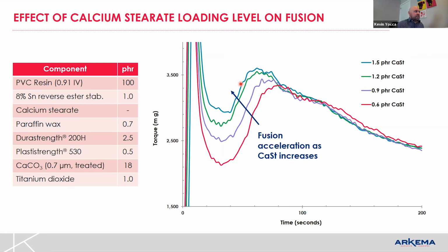Now, beyond these lubricants, there's obviously a library of them, from esters to complex esters, even mineral oils and other things. ESO can be used as kind of a co-stabilizer. So once you get into this and you start to see how many options there are, it's kind of endless. For me, I like starting with the basic building blocks. Typically adding things makes it harder to take them out later, but there is a time and a place for some of the specialty lubricants to get you some special processing that you might not get otherwise.